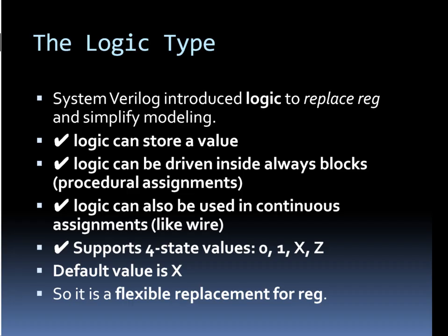Logic can be driven inside always blocks in procedural assignment, and it can also be used like wire in continuous assignments. It supports four-state values 0, 1, x and z, and the default value is x. So it is a flexible replacement for reg. Now let's see why we are using the logic type.